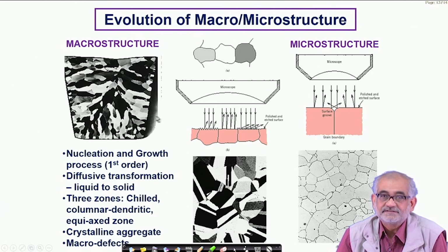And now inside this solid, I may have a single phase, and that phase we define in terms of the compositional and structural homogeneity bounded by definite boundary. So universe reduced to thermodynamic system comprising phase or phases, and the phase or phases may have differences in orientation leading to formation of various crystallites. And the phases are made up of components. I'm not saying elements or compounds, I'm saying components. They can be either element or compound.